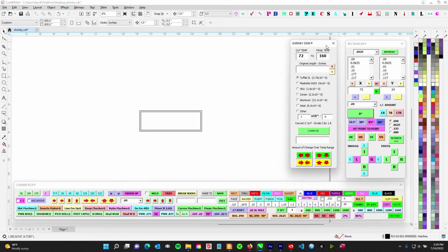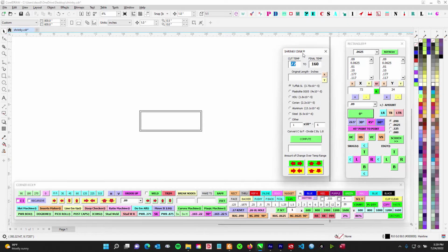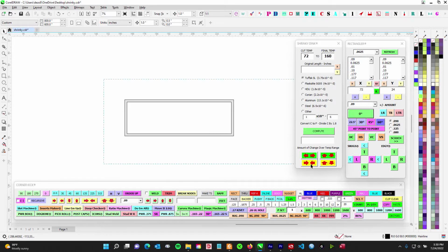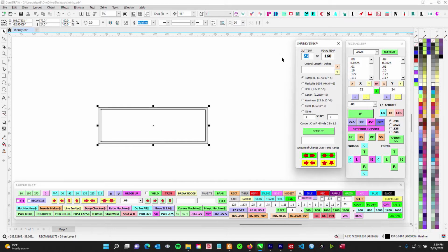Like I said earlier, you need those 4 measurements. You're going to need the temperature of the material when you cut it. An example for us out here in the desert is that our router tables are essentially glorified sheds. They have swamp coolers, but it can get pretty warm where we cut our sheets. Let's be generous, and say it's mid-March or April. It could be 85 in there, so we'll set the cut temperature at 85. And let's say it's going to have some dark vinyl and could get pretty hot, so just to be safe, I'm going to keep it at 160 for a surface temperature.